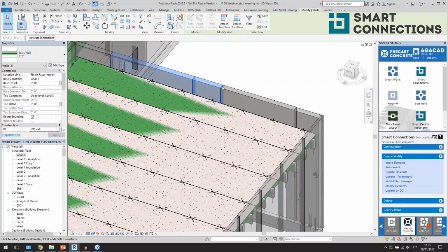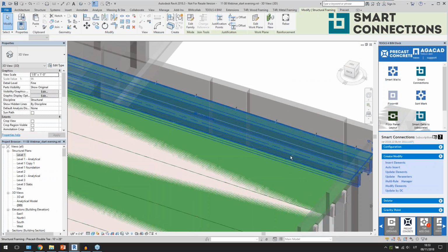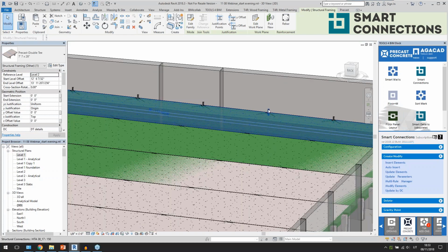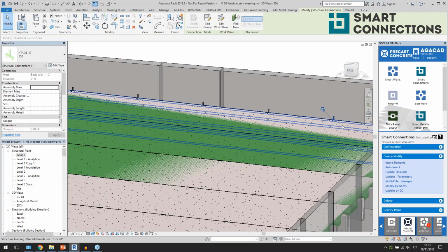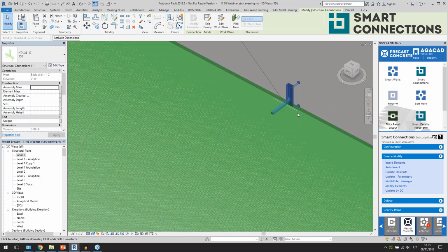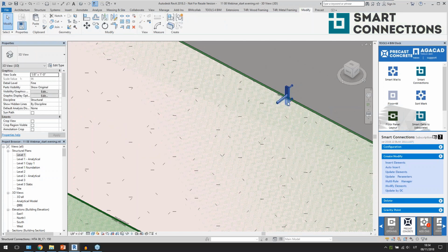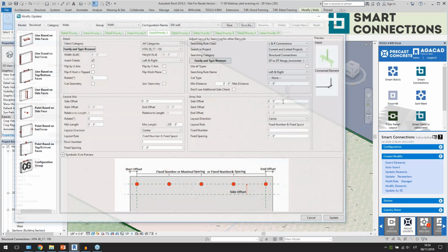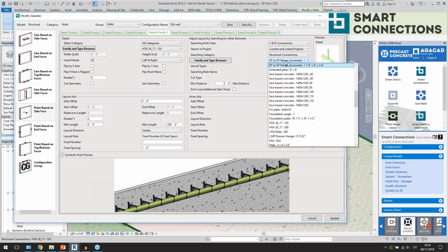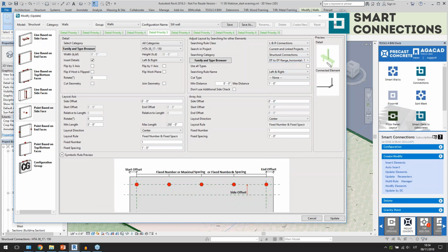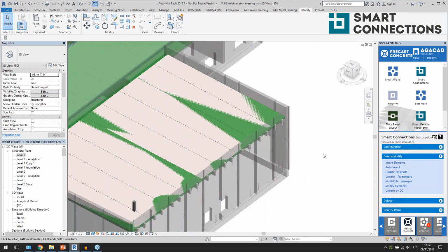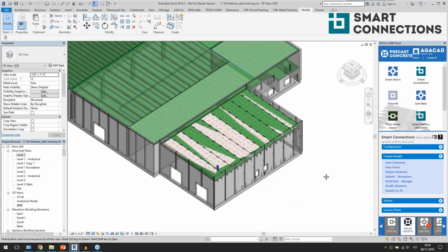All right. And you will see that now I have here slope, but my details anyway, they are not following the slope. They are searching for this detail, so for this connection. So this one is only inserted if I have that detail. So if I show in configurations, we are placing this one only if I have this one. Yeah, so that's the kind of stuff you can do with smart details.